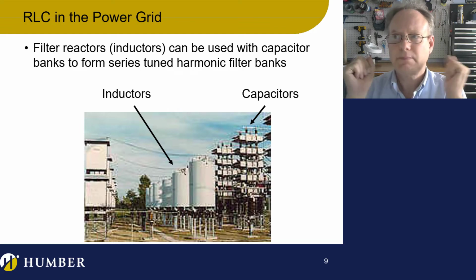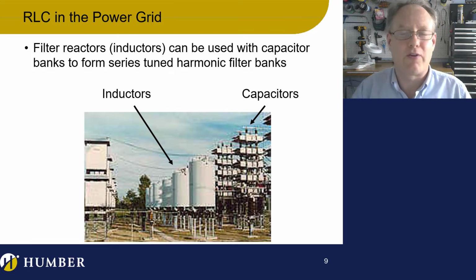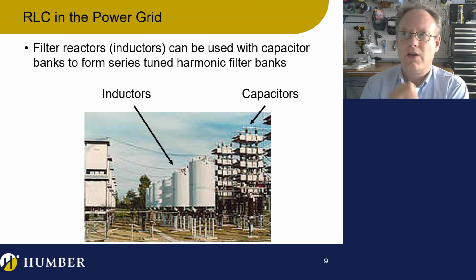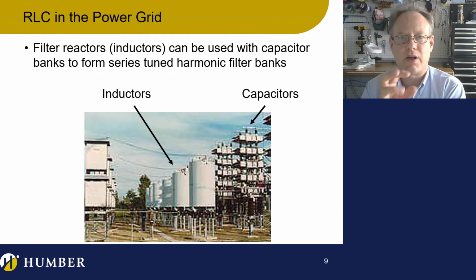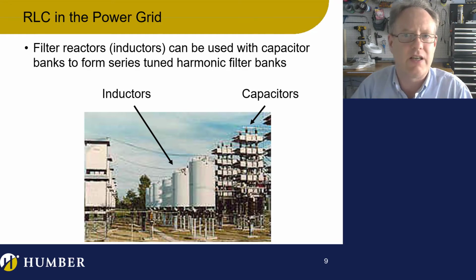This is really big. You know that there are a lot of inductors on the power grid. The power grid is supplying power to a lot of inductors, and actually things with capacitance as well. And that creates a problem, because if your current and your voltage are out of phase from each other, then when you calculate power, because power is just voltage times current, it creates inefficiency in your power.